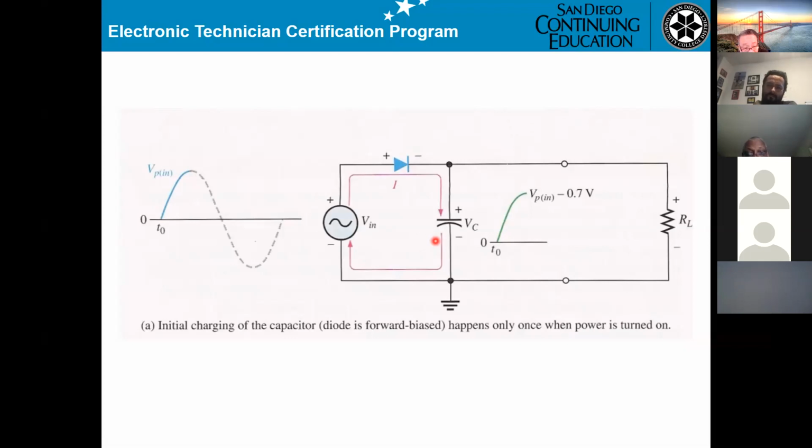It does not allow any DC current to flow through the capacitor when it is fully charged. That's a very basic thing you must know. And also the capacitor allows the AC to go through it. So that's why they say the capacitor is open for DC and short for AC. That means for AC the capacitor is like a wire. It allows the sine wave to get through it.